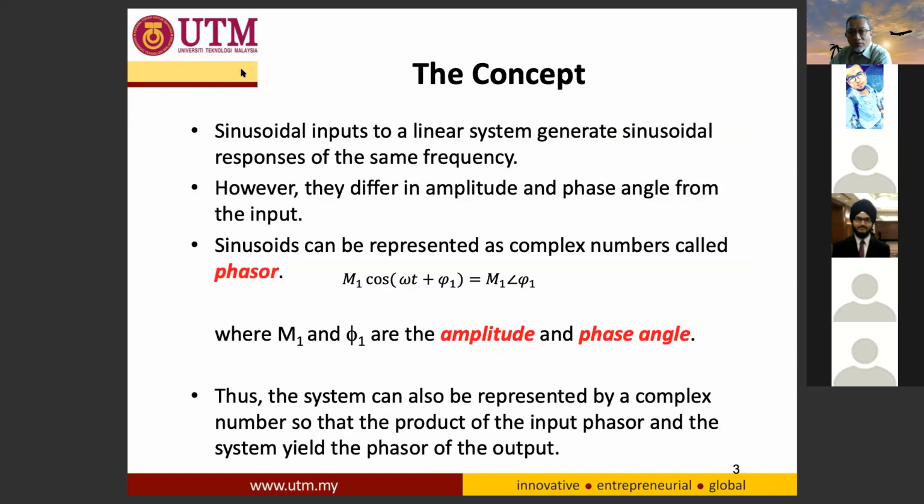So the concept of frequency response analysis is basically the input signal is not step anymore, it is a sinusoidal input, to generate a sinusoidal response of the same frequency. However, 2 important parameters are different, which is the input amplitude and output amplitude, and the phase angle from the input.